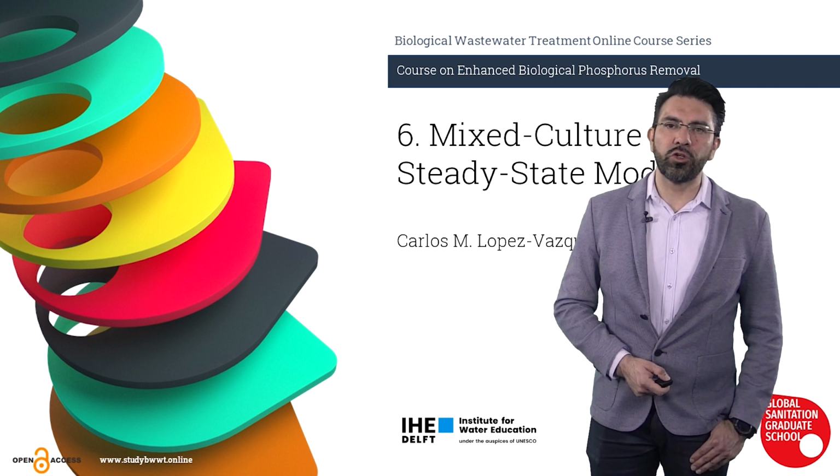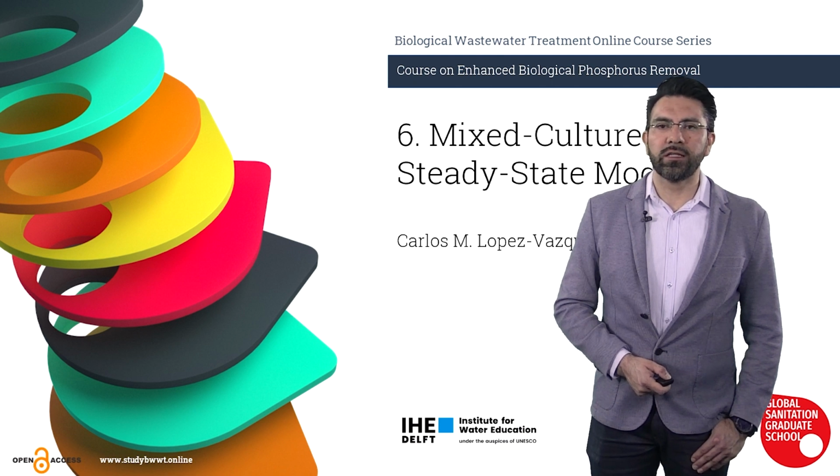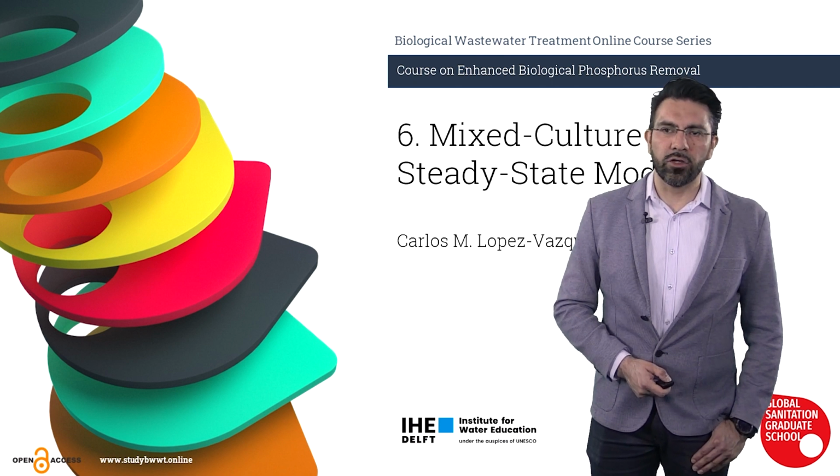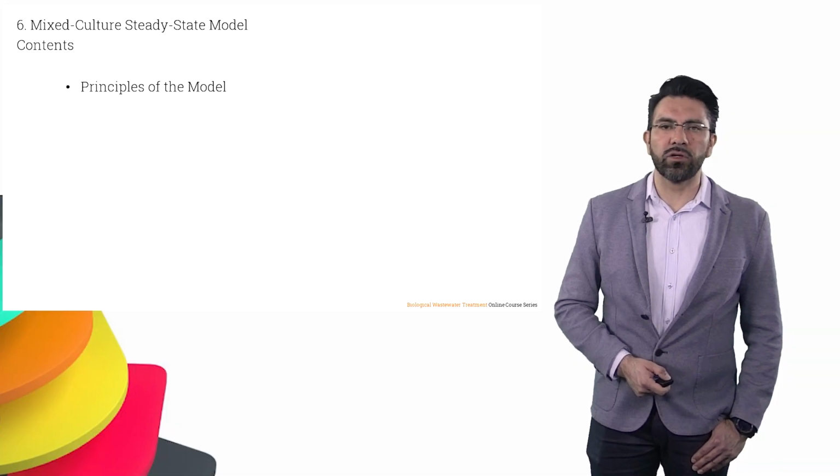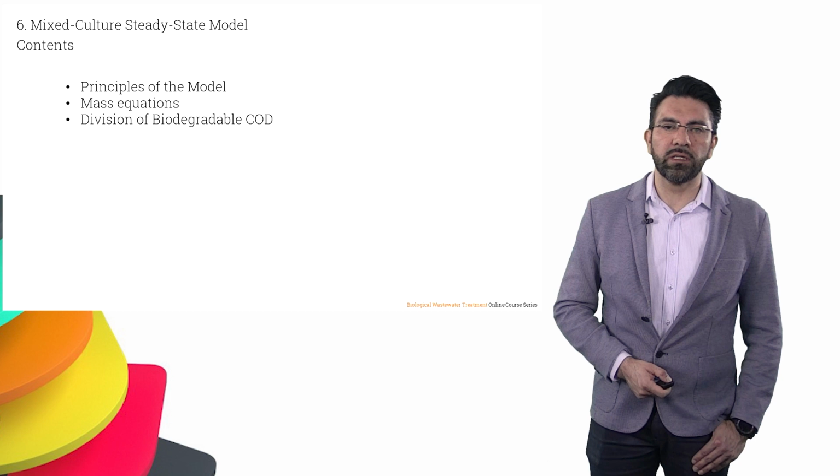And now I'm going to introduce a mixed culture steady-state model that is used for the design of the enhanced biological phosphorus removal processes. In this lecture, I'm going to talk about the principles of the model, the mass equations that compose this model.